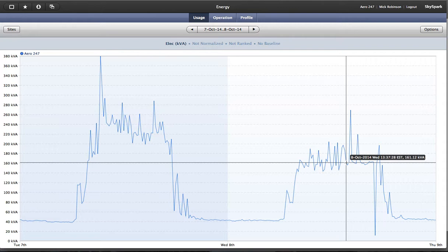From implementation, there were 2 occupants which complained, but they were also occupants that had been complaining about conditions prior to the implementation. So just to make things easier, those 2 zones have been excluded from the curtailment plans, and we're not intervening in those. But every other zone within the building is being managed, floating the set points, curtailing the demand without any adverse feedback from the occupants.